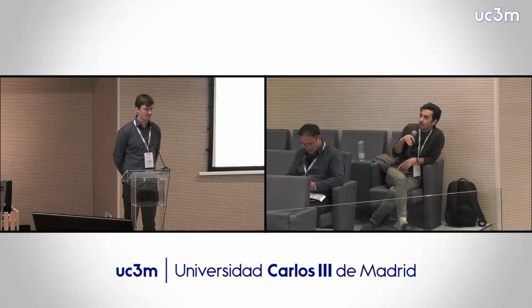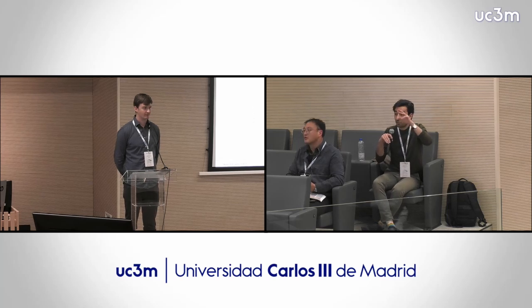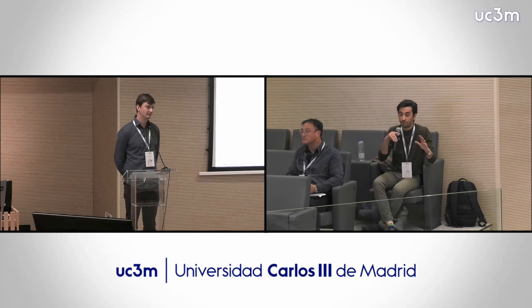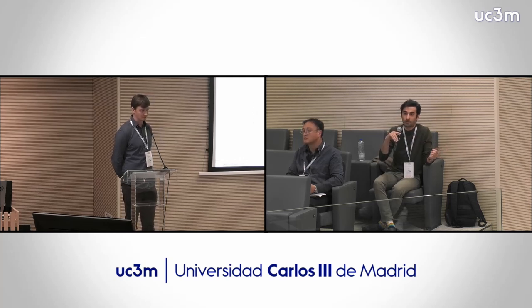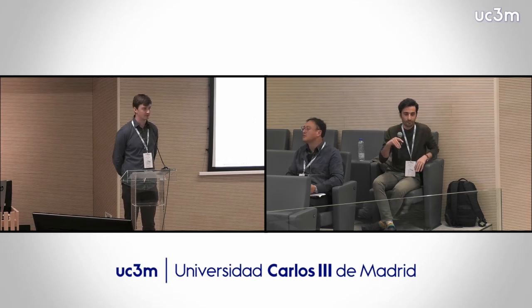Okay. And my second question is regarding your FSI model. Are you using matching grids, like from your panel method and your structural model? At the moment I do, but it's not necessary. You can also do a nearest neighbor interpolation. Okay, in that case you need some sort of algorithm to transfer data from, let's say, your fluid mesh to the structure mesh, right? Indeed. Okay, thank you.